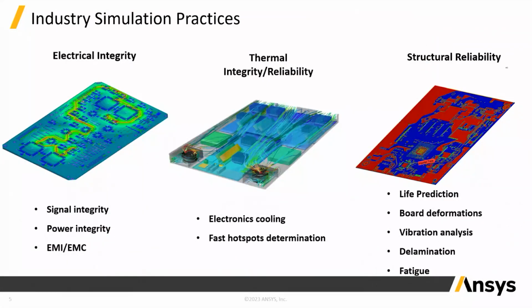Let's see what kinds of simulations we can do for the integrity and reliability side. From a very high level point of view, there are a few terms called signal integrity, power integrity, EMI-EMC. In a very simple way, signal integrity stands for: if I send some signal, like digital data ones and zeros, whether that is going to be received at the other end. Let's say from processor to memory, you are sending some ones and zeros, will you be able to receive and decode that same information at the other side? That is what signal integrity stands for.